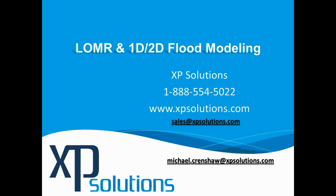So I think Sam Crampton at Dewberry has done a presentation for us on where they did a lot of this in areas where you could cover the Zone A very quickly and cost effectively and thoroughly with a 2D model, because what ended up going to FEMA was the delineation for a Zone A, right, because it's just approximate, and maybe the depth if it was needed, but not necessarily a model.